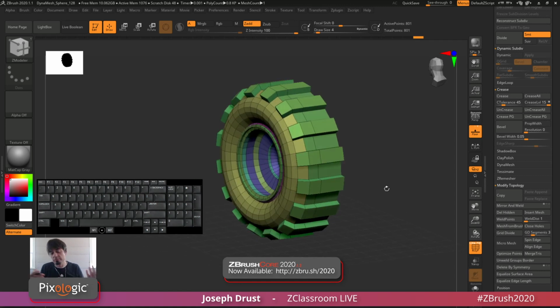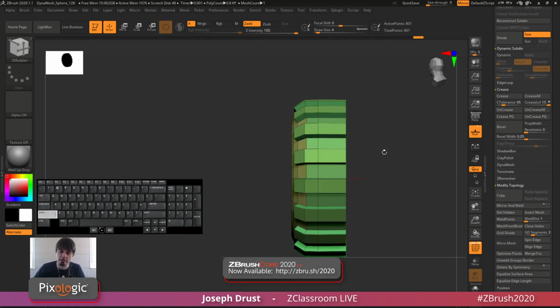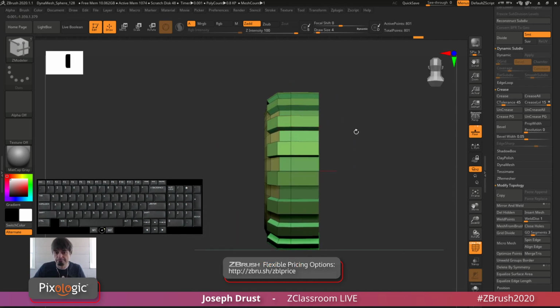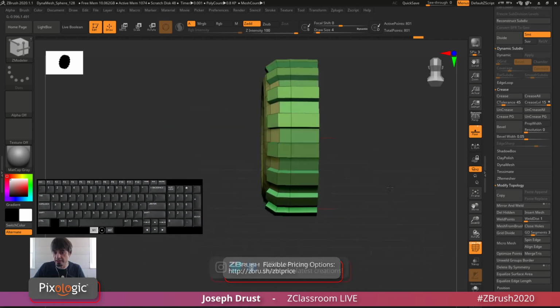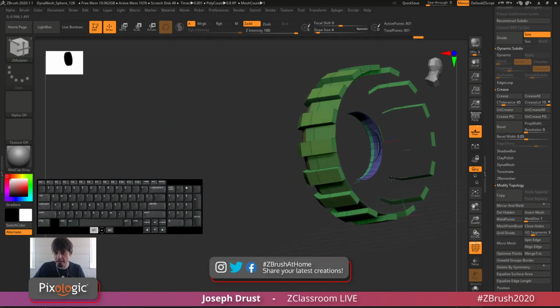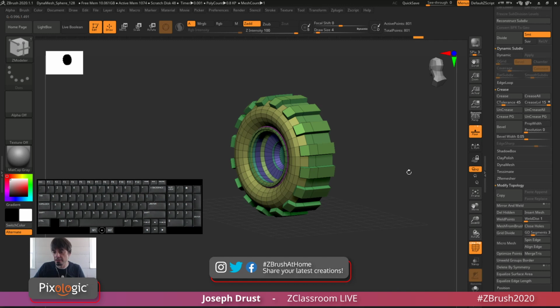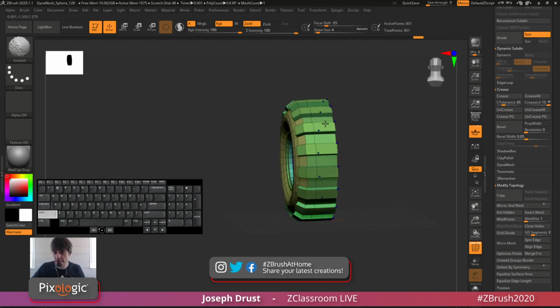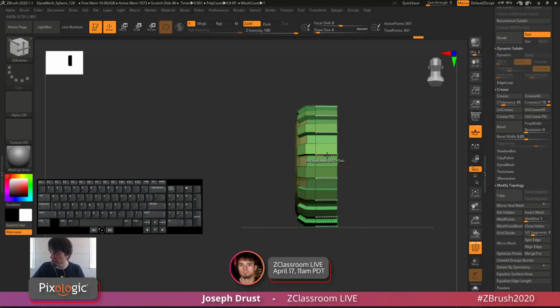And now you have a few different options. If you want the tread to have a design that's a little bit different, say on this side the tread goes here, and on that side the tread goes in between the other space, you can just isolate part of your tire like this. Once you have one of those parts isolated, I can make a duplicate and mirror it over. If I want the tread to have a symmetrical kind of V shape through here, I can now just perform a mirror and weld on this.